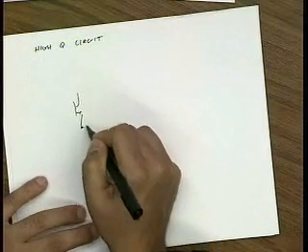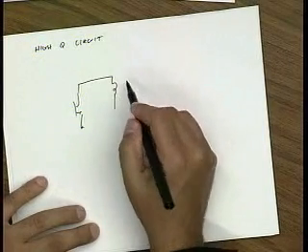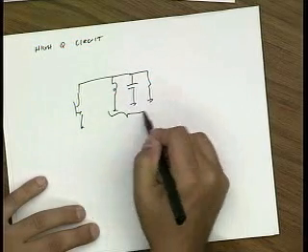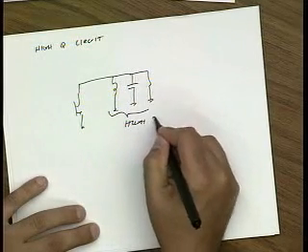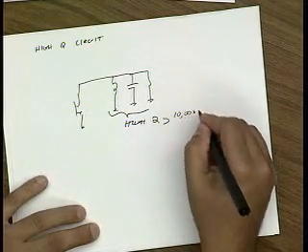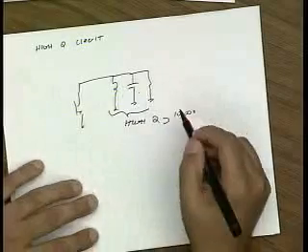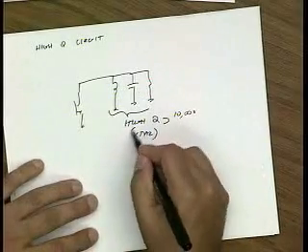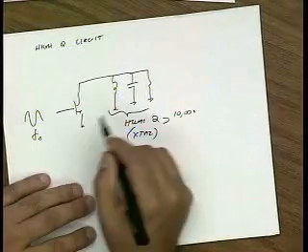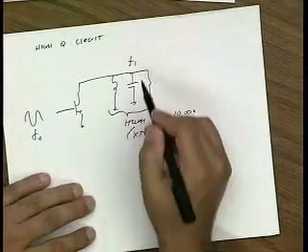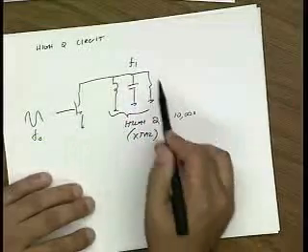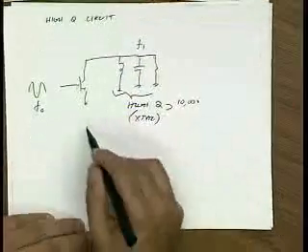So let's say I have an amplifier and the output has a high Q tank. And let's say it's really large. Let's say it's 10,000. Okay? For instance, this might be a crystal at the output. If I put in a sinusoid F0 close to this frequency, then I'm going to basically have to wait until the natural response of this crystal dies off.